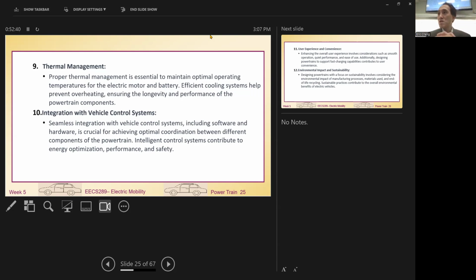The motor is a similar situation. The motor has good efficiency at 25 degrees C, but if you raise the motor to a high temperature, maybe under high power you go up to 80 degrees C, the efficiency of the motor will be really poor. The torque will be degraded. You are not able to provide full torque, only 80% torque, maybe 70% torque. So that's why thermal management for this kind of motor design is so important.